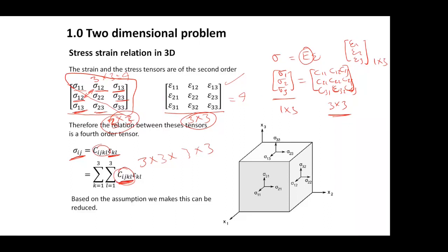All right. So this is how it connects. This is the most general case. Now, for the vast majority of the applications you will be working with in your life, I suspect the vast majority of you will not need this, since you will be working with something simpler. Now, in the most general case, I said we have 9 components for the stress, 9 components for the strain, and 81 components for the material properties, 81 components. Okay?